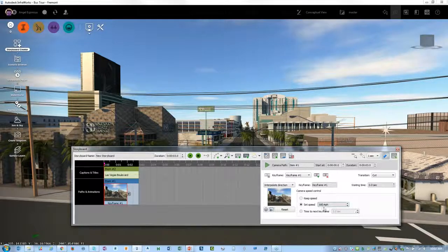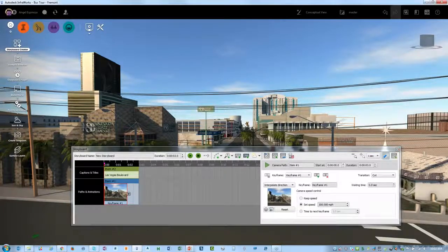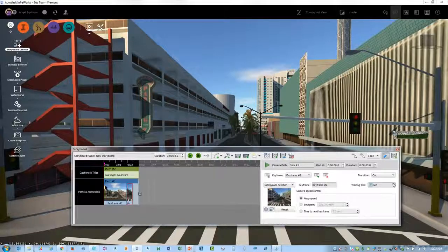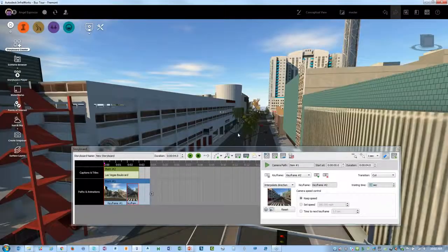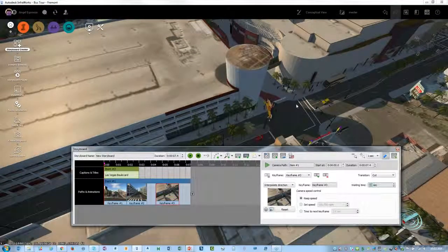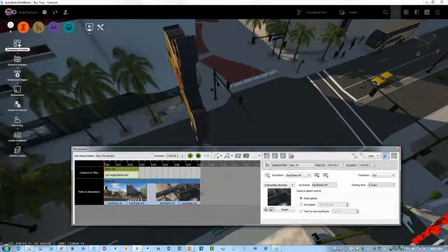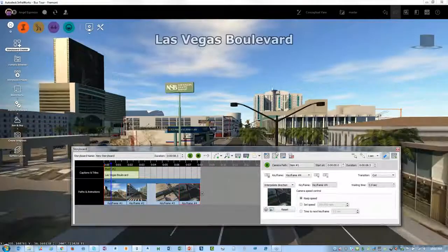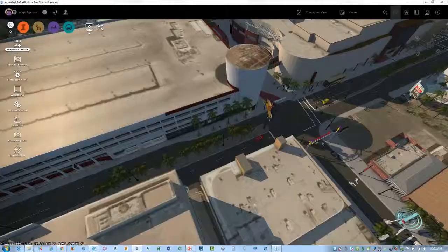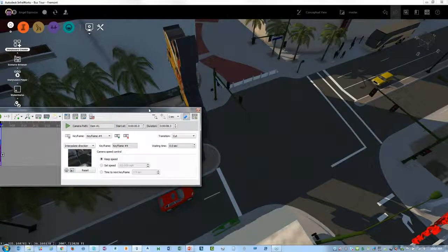And we're going to say, let's go to the next frame. So I'm going to go here, add a new keyframe. I'm going to pause there for about 2 seconds. Maybe I want to look overhead, add a new keyframe, pause there for about 2 seconds, and then zoom into this area, and then end there, and I'll hit OK. Lastly, I'm going to go ahead and press play and move this out of the way, and there we see, get from the first to the second, pause for 2 seconds, get to the next, pause for 2 seconds, go to the last environment, and all of that is part of the process.